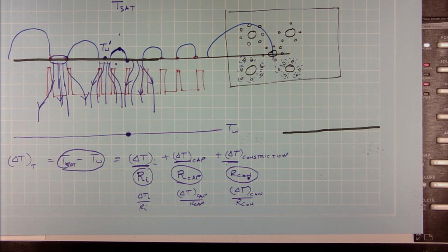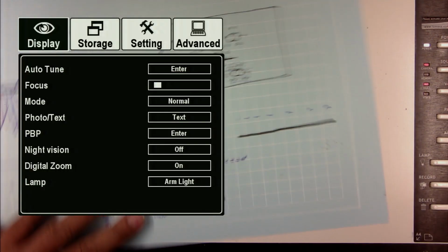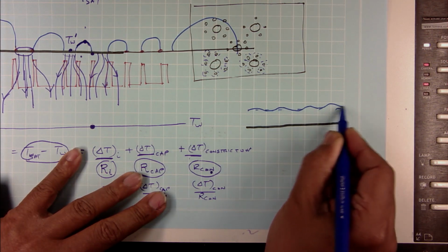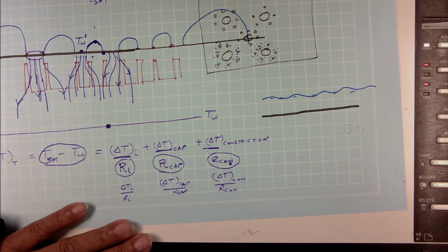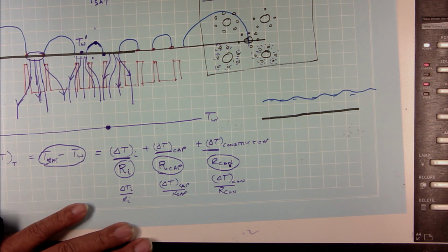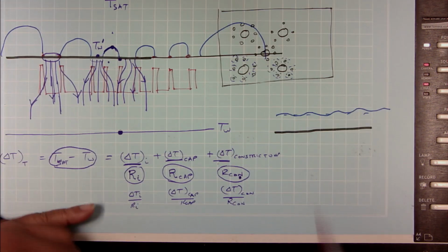Okay, I will have a film of liquid, and I might have some ripples on this film of liquid, and ripples will increase your heat transfer. I do not have time to go through it, it is there in your handout. You will see there is one section where it discusses the effect of the ripples. The ripples can actually improve your heat transfer by a factor of about 10% versus when you do not have ripples. Okay. So, but that aside, this is fairly straightforward because I will have a resistance at the interface.